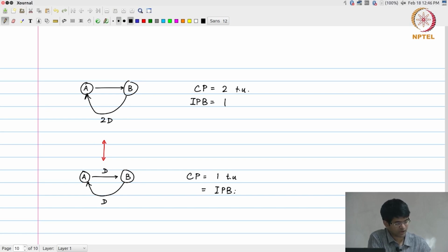If I look at this, what have I actually done over here? I have essentially taken this as my cut set. Is it a feed forward cut set? No, because one edge goes from A to B and the other edge goes from B to A, but I have still applied movement of registers across this cut set. Effectively, the way that you can look at it now is, I can choose any cut set, it need not be feed forward alone, it is just that in one direction if I am adding registers, in the other direction I should be able to subtract registers,